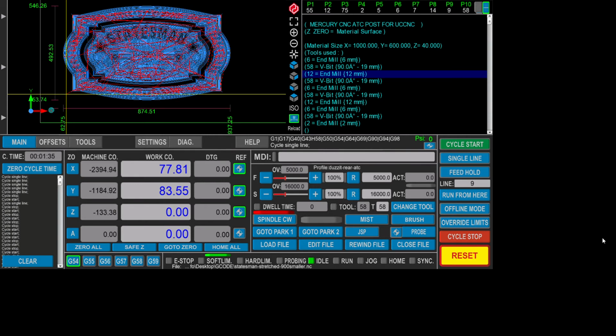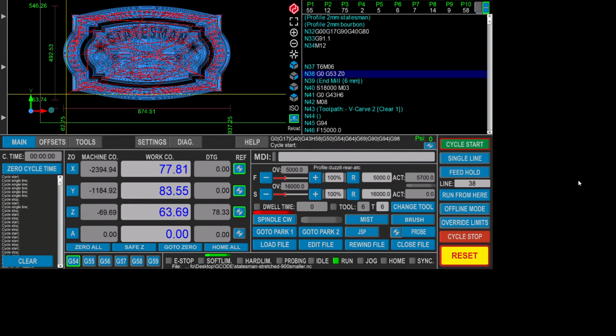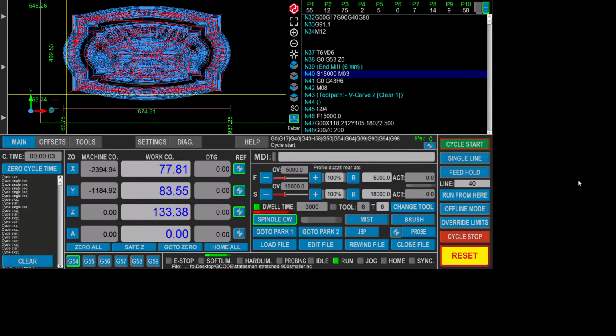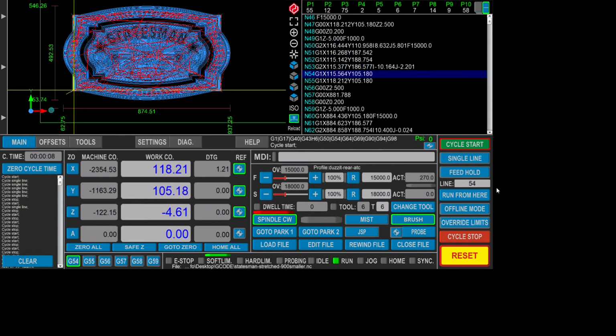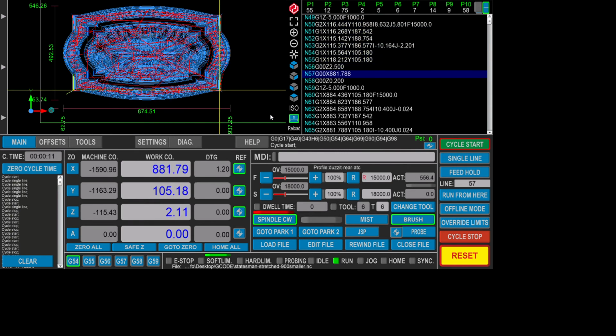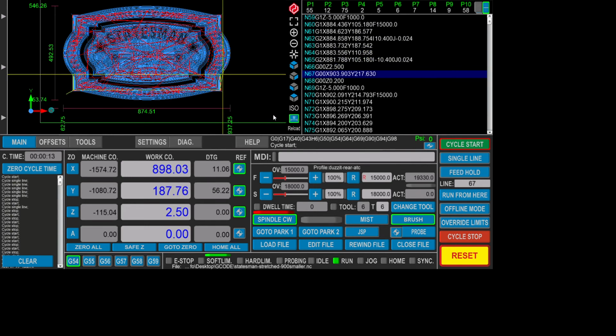Okay. Now at the moment the machine would be loaded. It's got tool 58 in it, which is shown here in the grey box. Now basically from that we can press cycle start. The machine is loaded, it's zeroed on the X, and we can just press cycle start. You can see there's a slight delay at the start where it waits for the spindle to kick in, which is about 4 or 5 seconds on the machine. And now you can see the green line starting to do its work, which is where the spindle position is.